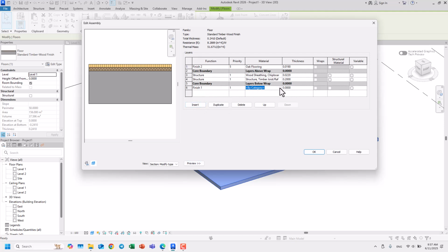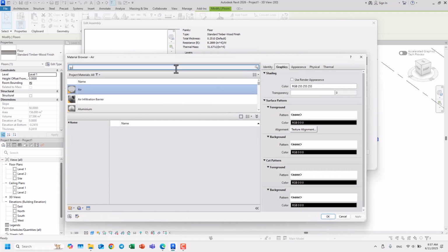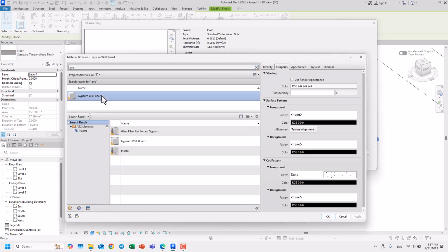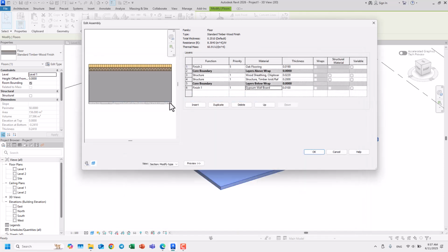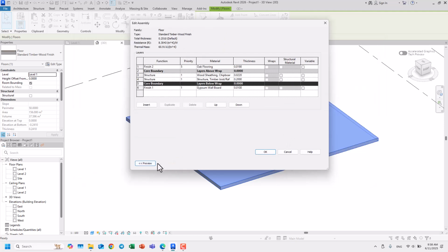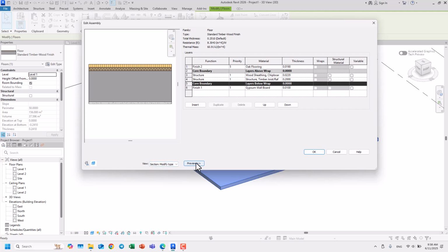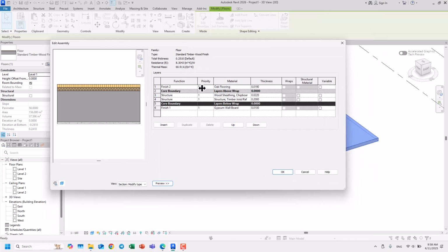layer, and I will give it a thickness of 0.01. I'll make it gypsum. Okay, I will add gypsum here, and okay, now it's a gypsum layer. You see, you just put this as a section, and you can collapse or open it, okay, like this, and this will calculate and the thickness will change. Okay, the thickness was different than before.